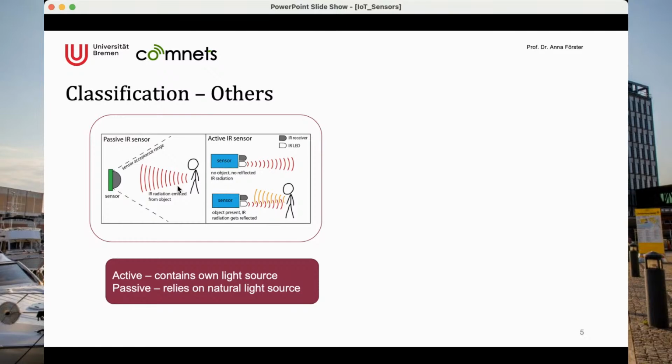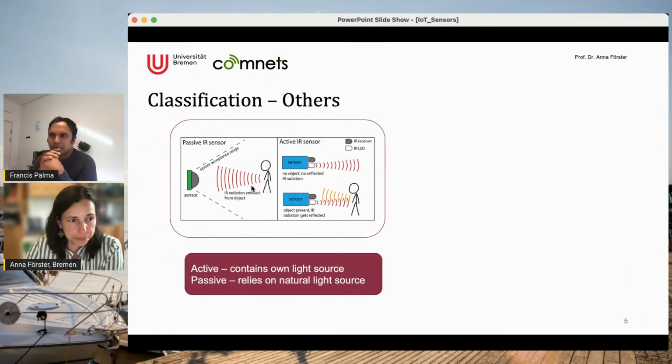So with active sensors, you have the so-called split event, which means that you start the measurement, and whenever the measurement is available, you get a software interrupt back to understand that, okay, I have my measurement back. So this differentiation is very important for us, because it creates a lot of implementation problems.